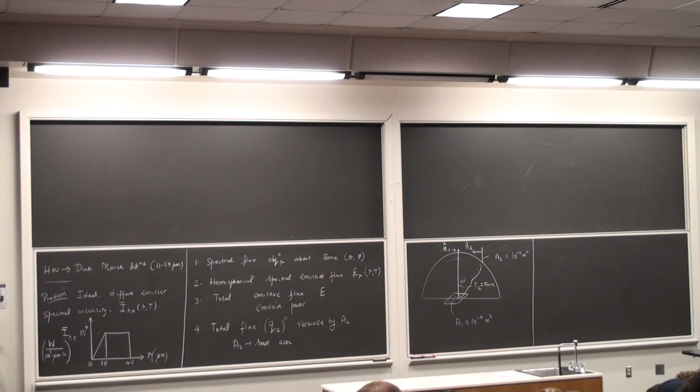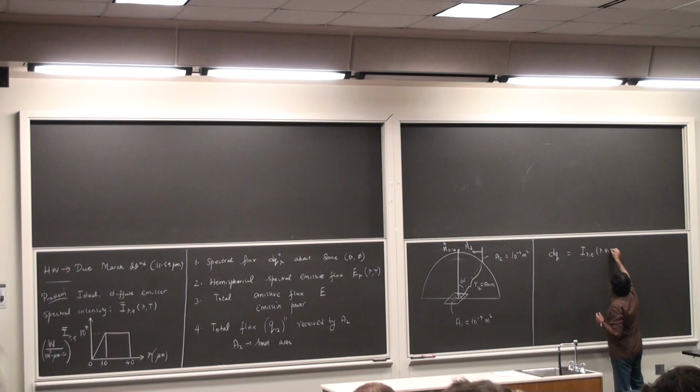I'm going to start from the definitions. So we define intensity in the following manner, or rewriting the formula from before: dq is I lambda,e of lambda, theta, phi, d lambda, d omega. Notice we are looking at the emission characteristics at this point in time.